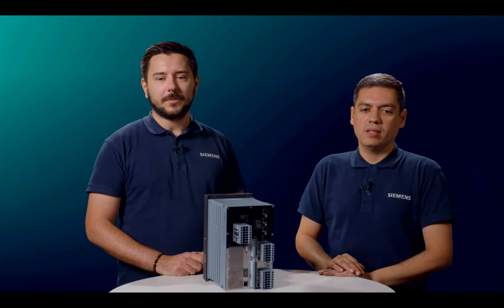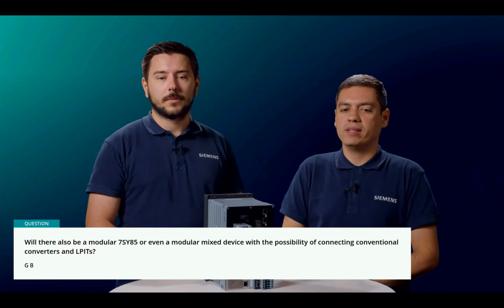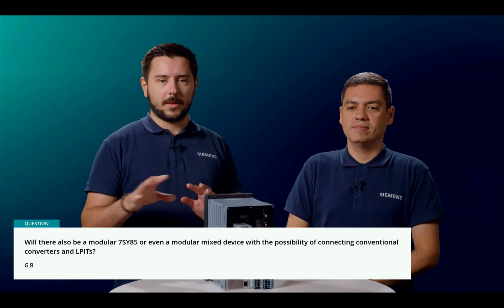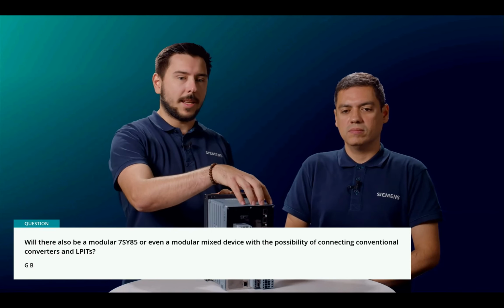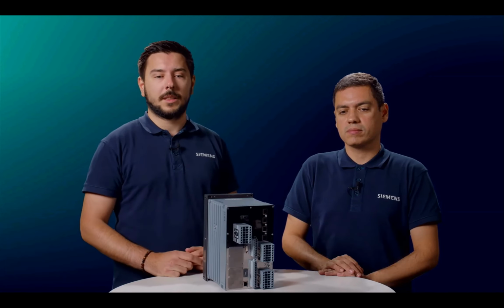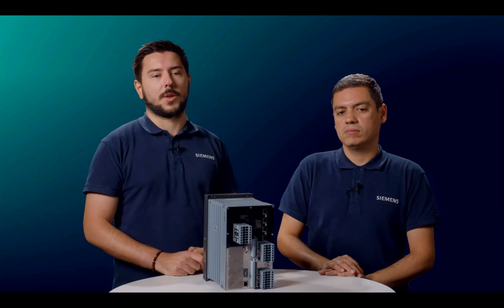Let's see another question. Will there also be a modular 7SY85 or even a modular mixed device with the possibility of connecting conventional converters and LPITs? Yes, short answer, yes, there will be. It was also visible on the roadmap. The 7SY82-85 will be a modular device with an LPIT module as a base module. But of course, also probably the IO241 will be available as an expansion module, which can be used with every SIPROTEC 5 modular device. Therefore, mixed combinations are also possible.